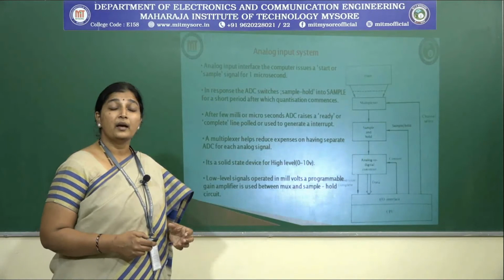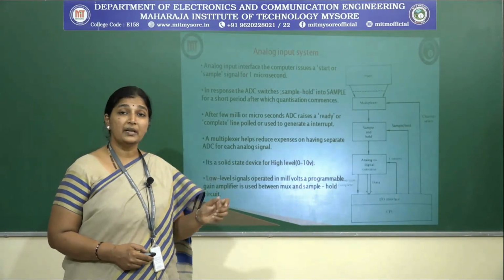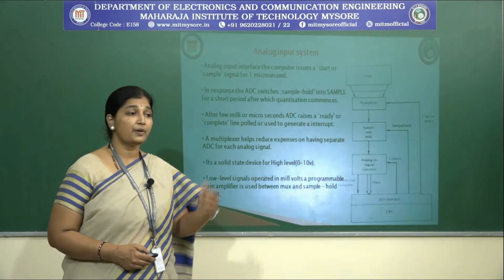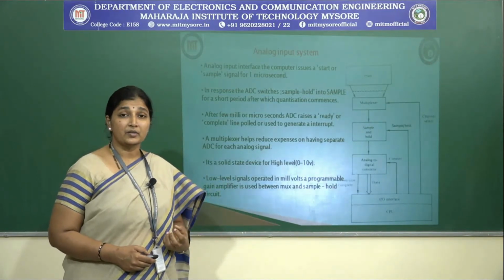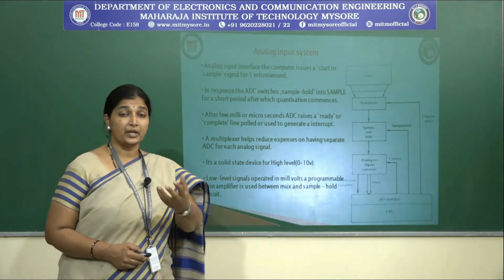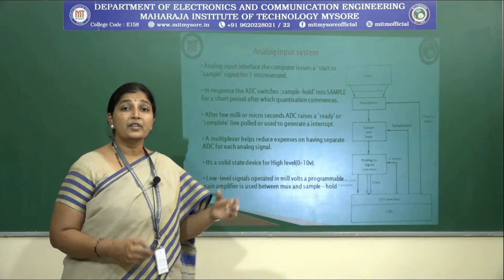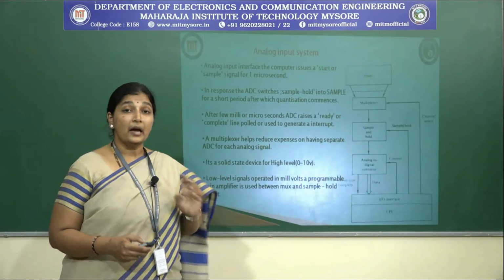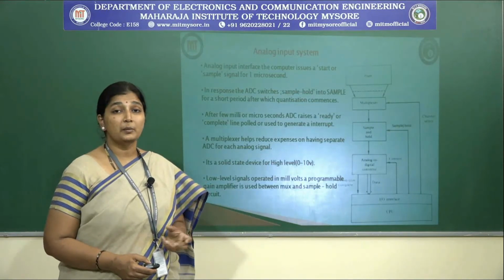So instead of having one A to D converter for each and every interfacing unit that you're going to connect externally, for example, if you have some data being extracted from a plant as pressure, and you have another analog signal taken as temperature, if these are two different entities, then you would need two ADCs. Instead, you have what is called a multiplexer.